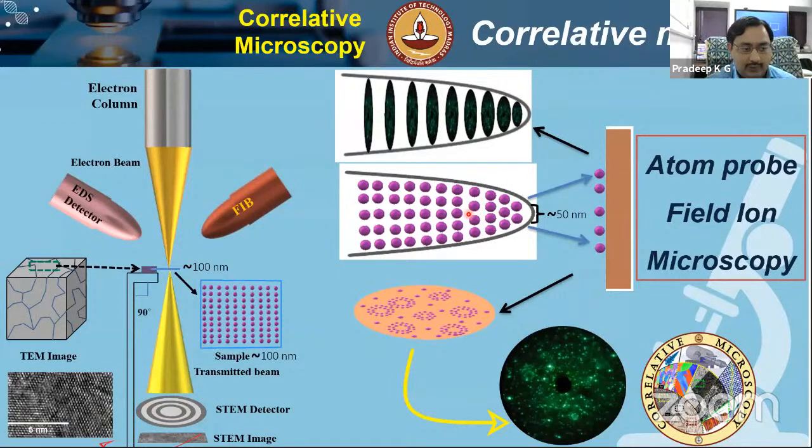But the interesting challenge we see, for example, is the samarium system that you have shown earlier. We have noticed that samarium quickly reacts with hydrogen and forms samarium hydride. And some of the diffraction that we have been doing in the SEM seems to be a challenge. We are unable to get diffraction patterns when we work with elements like samarium, which seems to have a very strong affinity with hydrogen. So those samples may be tricky, even if you want to study hydrogen effects in these materials. But for most steels and superalloys, I think charging hydrogen with deuterium solves the problem.